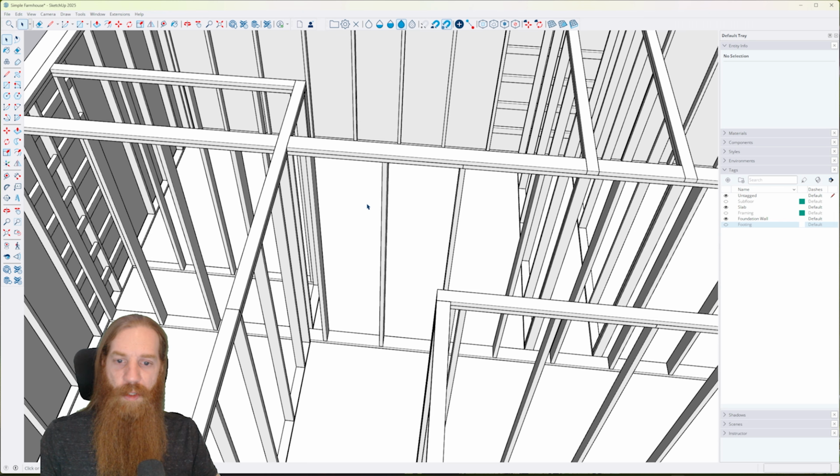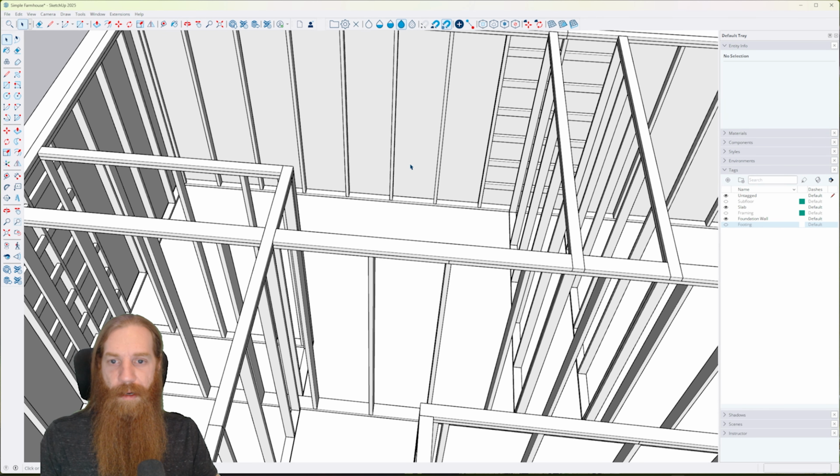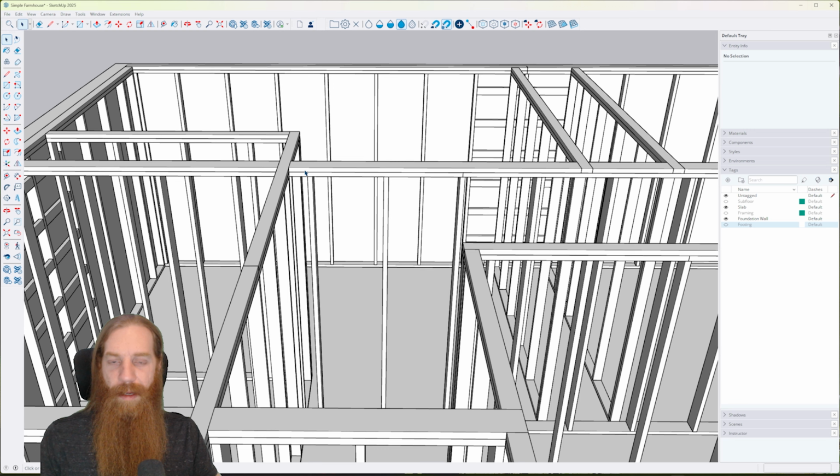And you're nailing all of these top plates directly into the joists above, so they are going to be anchored very well throughout the entire wall, because the joists give you a nice solid structural member to nail those into at the top plate.